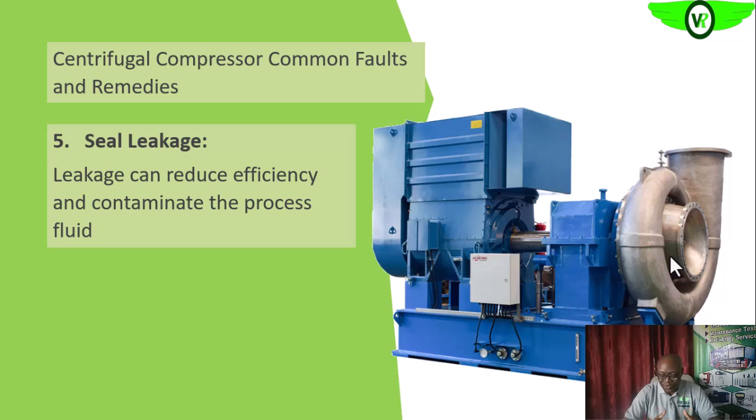If the gas is corrosive and it is exposed, the other components of the compressor unit like the bearing and what have you are exposed to the discharge gas from the leaking seal, and that can affect the bearing or other components of the compressor. So we want to remedy the situation once we observe as such.